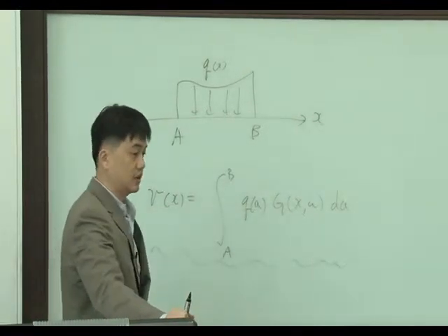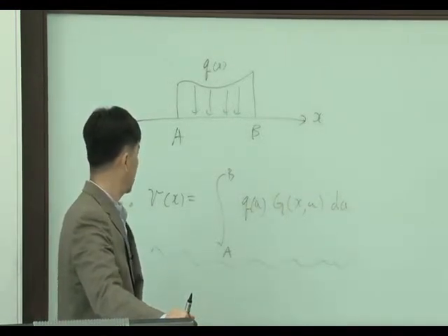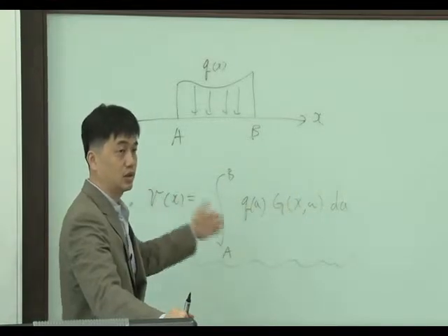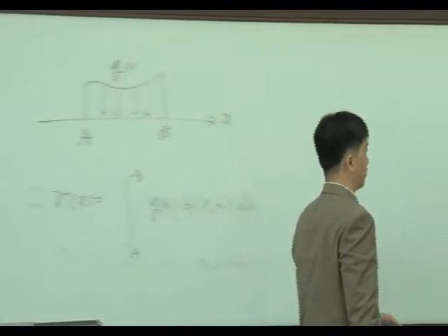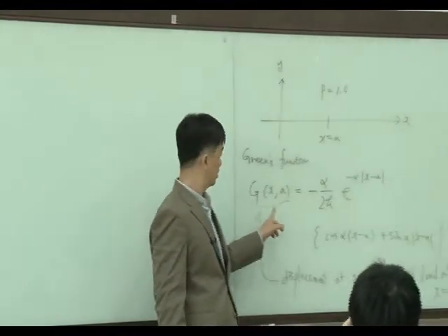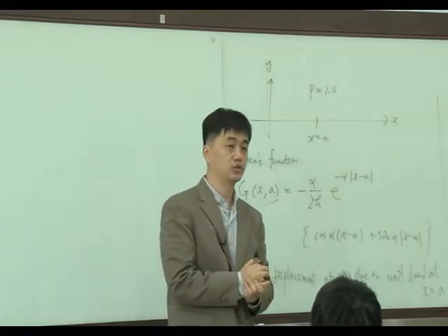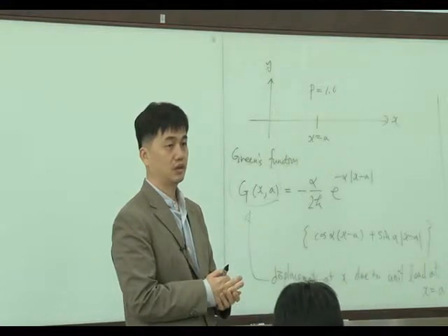So for the general case of loading, we can calculate the displacement by using Green's function, which derives from the solution of the unit load case, right?